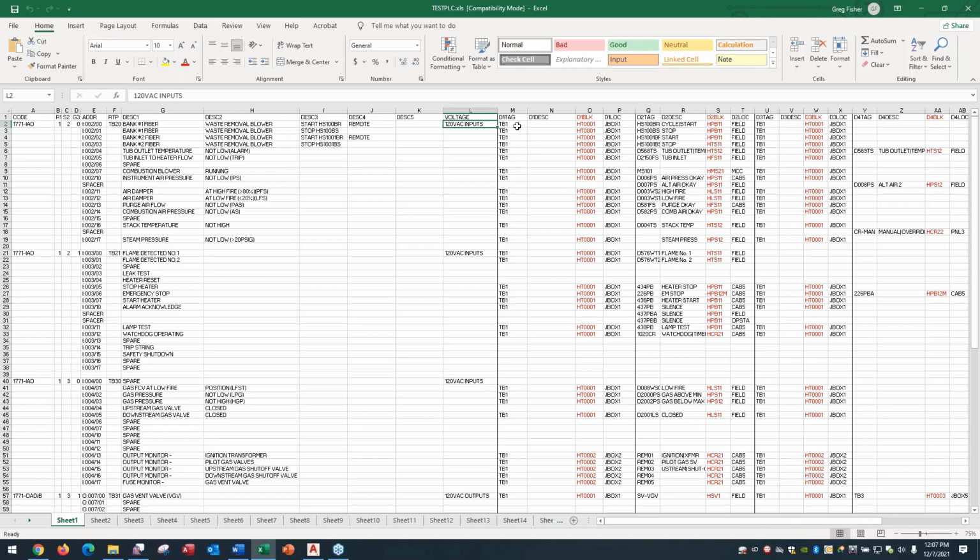And as you can see here, this particular one is set up for, you have to plug in the tag, the description of the component if you have one, the name of the block itself, the name of the symbol itself. You have to know what the name of the symbol is that it's going to use. And then we have a location field as well. Now, when I get back into software, you're going to see how there are more fields available that you can add to the spreadsheet and then in turn map them to the utility when you run it. And I'll explain that in just a minute when I get into the software.